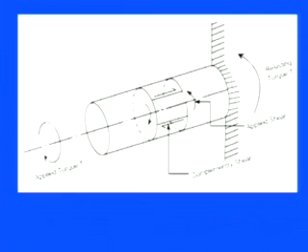So under the application of these two shear forces, or these two shear stresses, the bar is perfectly balanced, and this diagram clearly shows this phenomenon: we have an applied torque, a resisting torque, an applied shear stress, and a complementary shear stress, both acting at the same time, exactly equal and opposite. So whatever the torque or shear stress application, this uniform bar is well balanced under it. This is the exact phenomenon we wanted to discuss.